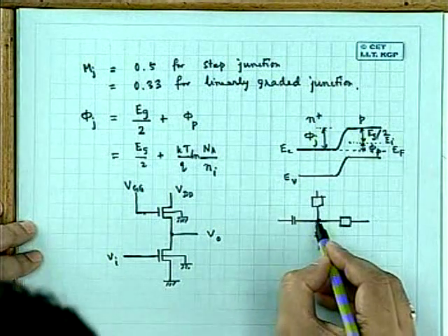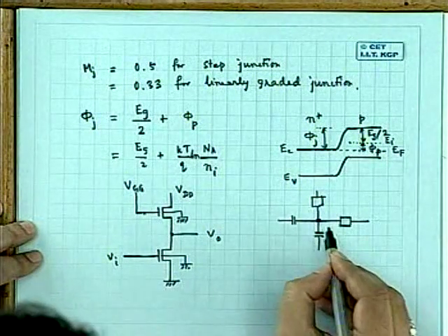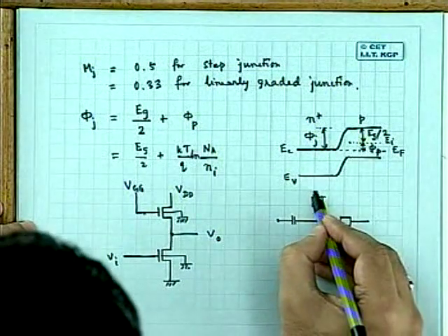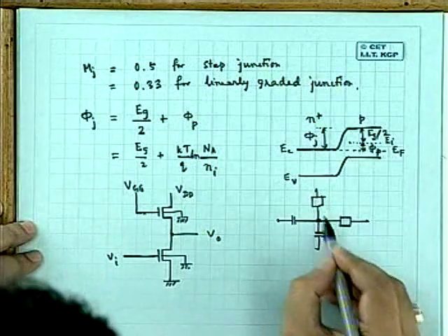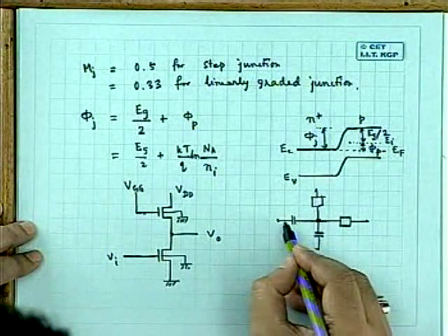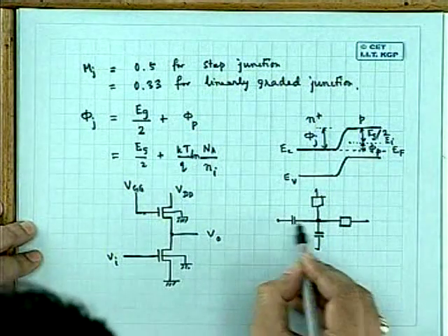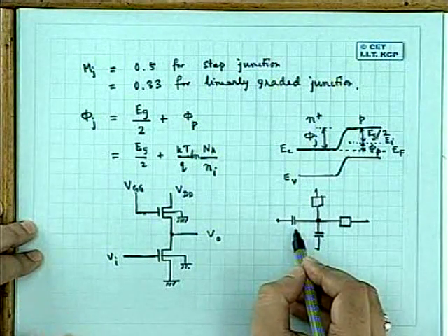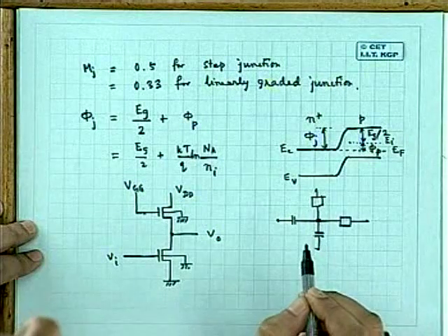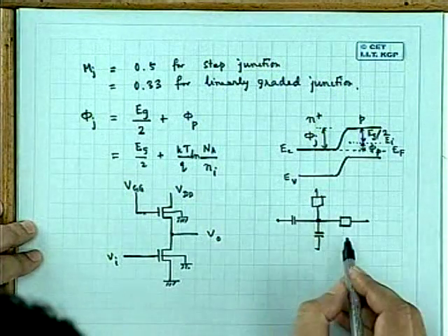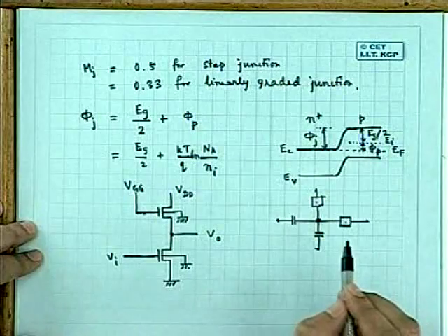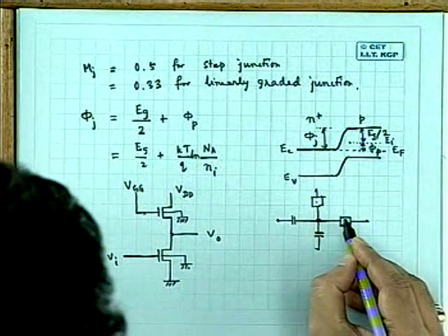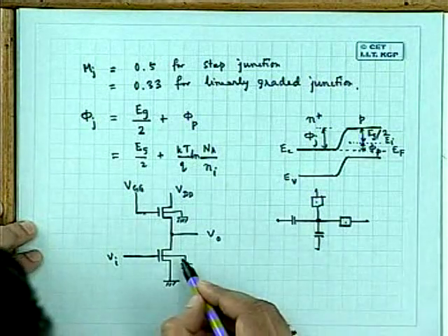Now, what will happen? In nodal analysis, this is all in terms of voltages, isn't it? So the current in each component is equal to the voltage between the adjacent nodes divided by the total impedance. So far as these devices are concerned, I mean the resistive part I am saying.